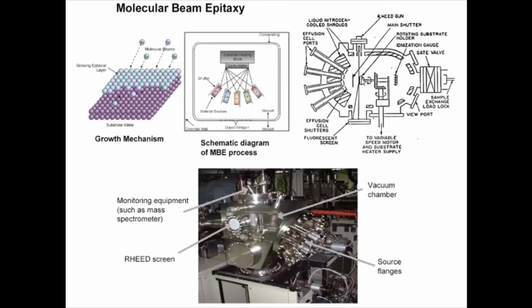And the advantage of MBE is that you have a RHEED screen, where the reflection high energy electron diffraction pattern can be seen. You can see whether the growth is occurring, whether it is crystalline or amorphous. So those details can be monitored.